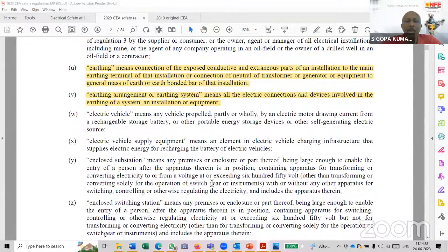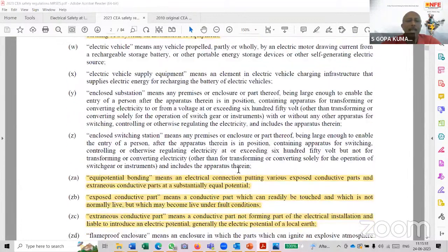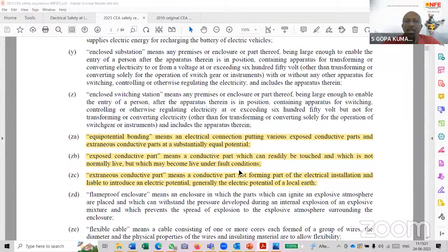If you look at IS 732, I think clause 5.1.6 or so, there is a requirement of limiting the leakage current in an electrical equipment or appliance. For a fixed installation with current-using equipment of more than 32 amps, the maximum allowed leakage current is 10 milliampere. If the leakage current is more than 10 milliampere, we are supposed to make a reinforced protective measure. And one of the reinforced protective measures is to have two connections. So technically, these two connections are required. You can even see it in IS 732; just search for reinforced protective measure and you will find it. So basically, this is a requirement. I hope, Mr. Amrit, this is clear.